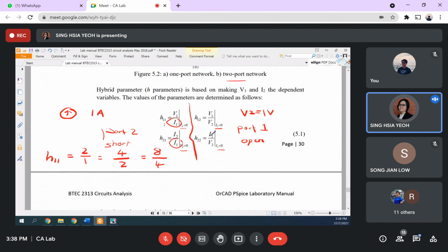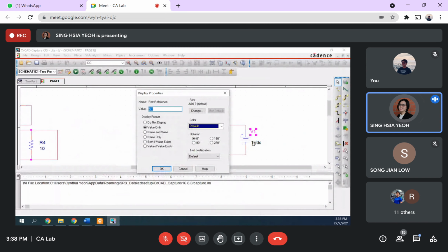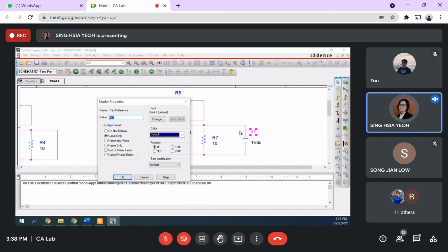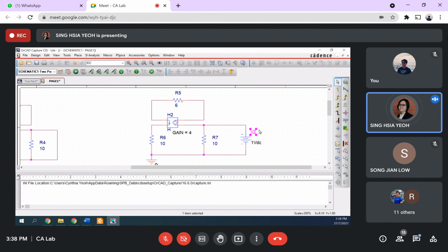When I say V2 divided by I1, you cannot say, why is this V1? Of course, this is V1. This is a name from PSpice, so you have to rename it to V2. You should know that this is actually the port 2 side. So actually, this is V2.